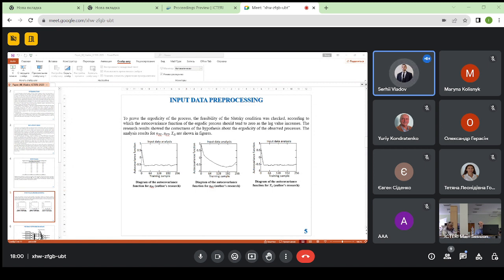The task of developing an algorithm is reduced to modeling a mathematical expression to calculate the specific values at each step. Calculations in the multidimensional Kalman filtering algorithm were based on the dispersion of the model and sensors along the coordinates of thermogas dynamic parameters which are recorded on board the helicopter, obtained by statistical processing of flight test data of the TV3117 turboshaft engine.